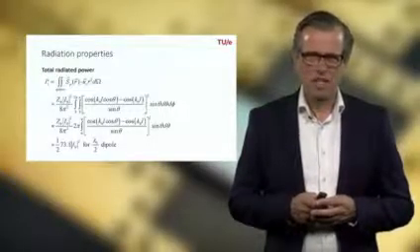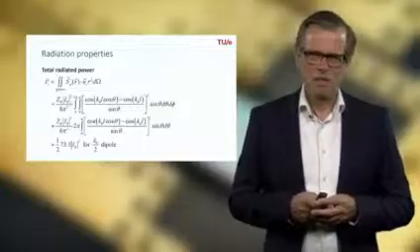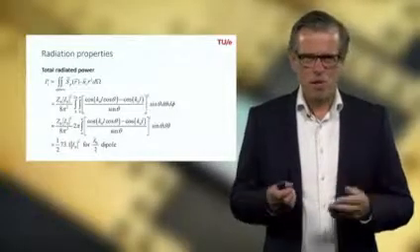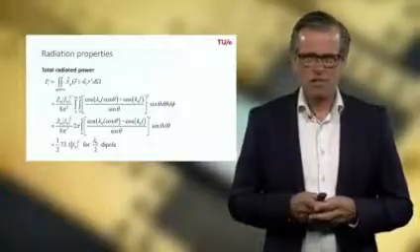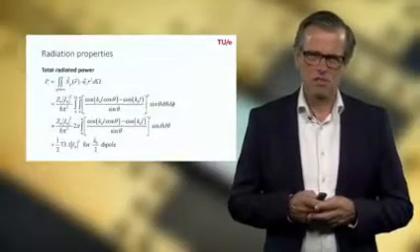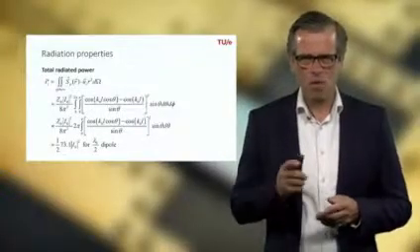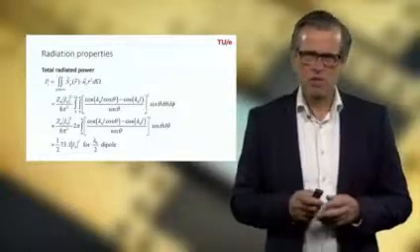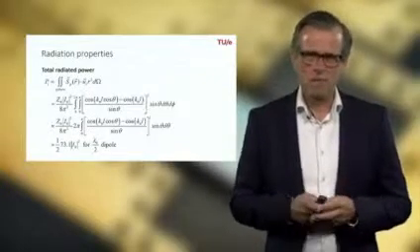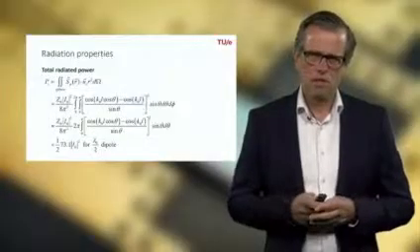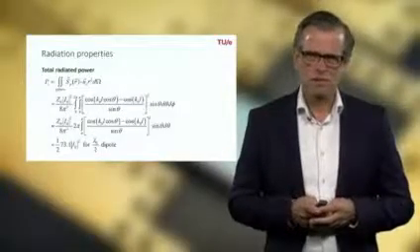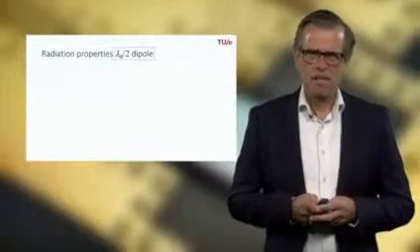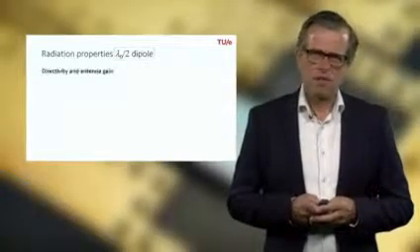So you already recognize here the expression for the total average power when you would have a circuit with a resistance of 73.1 ohm. Well, I will come back to that in a second. So this holds only for a half wavelength dipole, but you can do the integral also for other lengths, of course. So let's continue with the radiation properties for a half wavelength dipole.